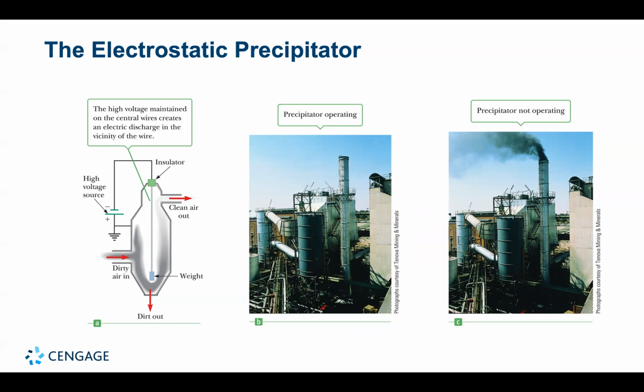An electrostatic precipitator is a device that removes particulate matter from combustible gases, which is used to reduce air pollution. It's especially useful in coal burning power plants and in industrial operations that generate large quantities of smoke. Systems currently in use can eliminate approximately 90% of the mass of ash and dust from smoke. Unfortunately, a very high percentage of the lighter particles still escape, and they contribute significantly to smog and haze.